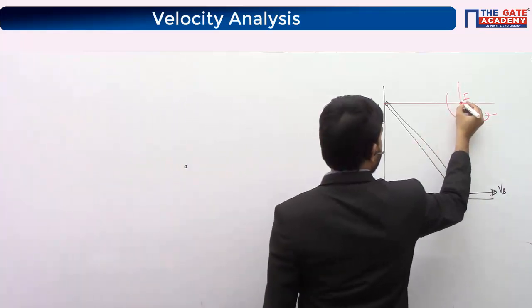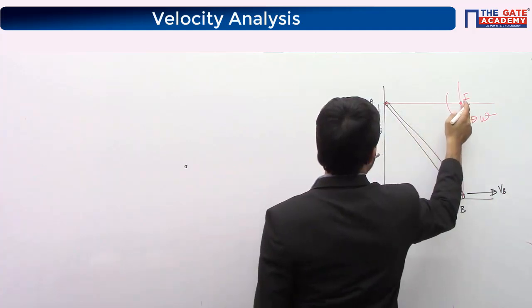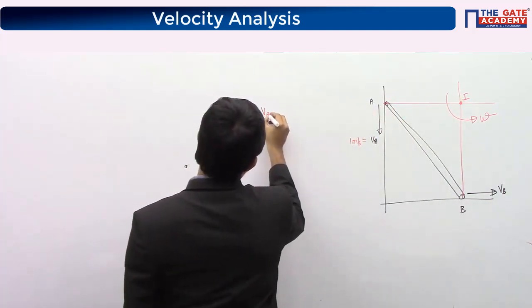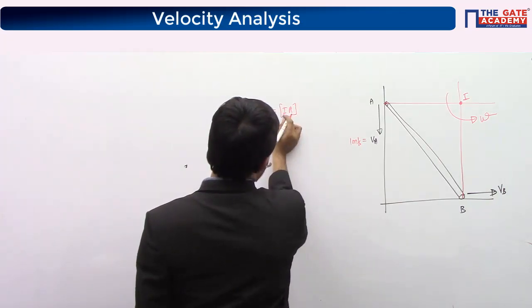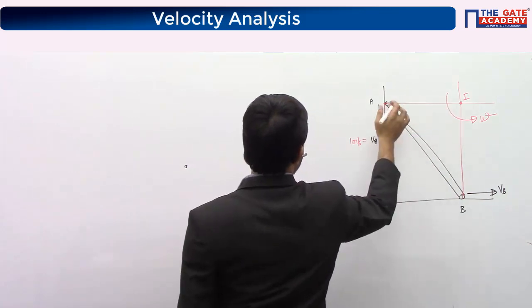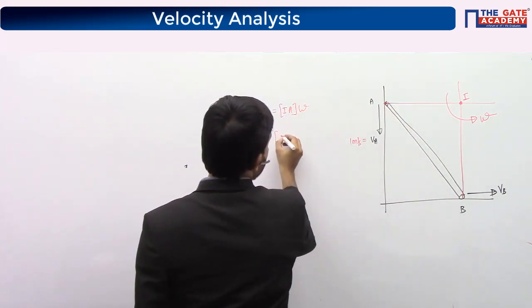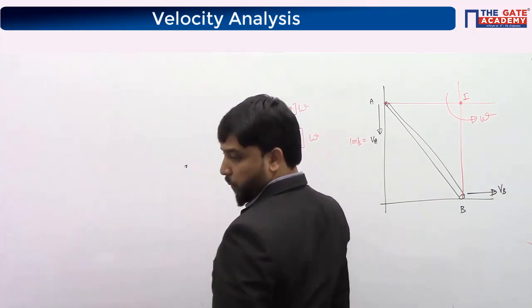So if this is the center of rotation, and you want to find the velocity of point A, I told you, right? It's r times omega. What is r? IA. R is the distance from the center of rotation, which is I, to point A. The velocity is given as 1 meter per second. So try to find out IA, and then you can find omega.